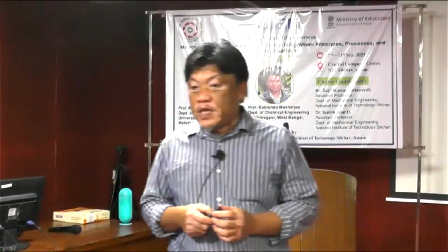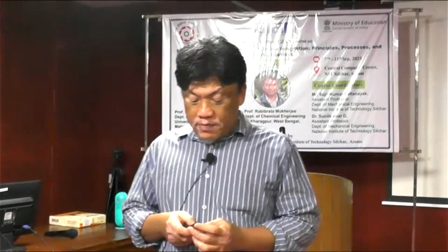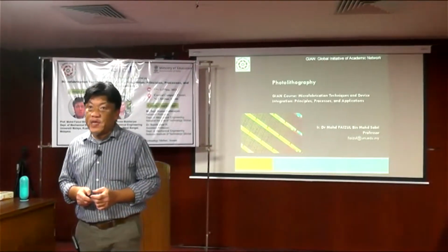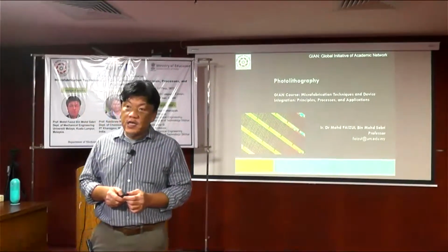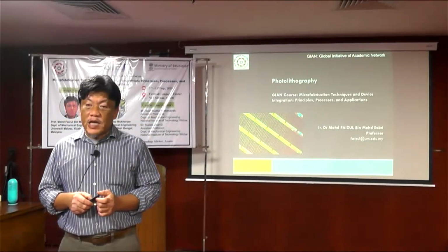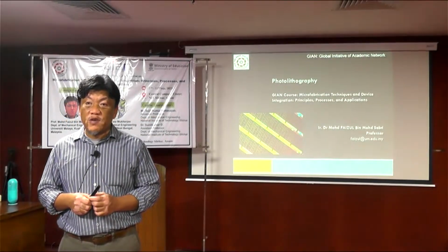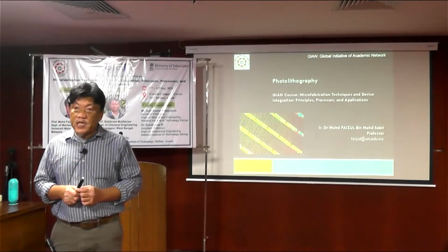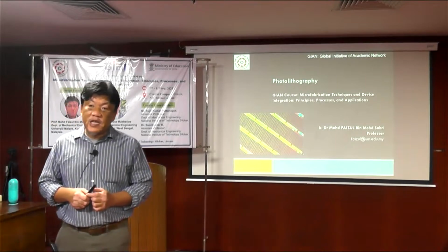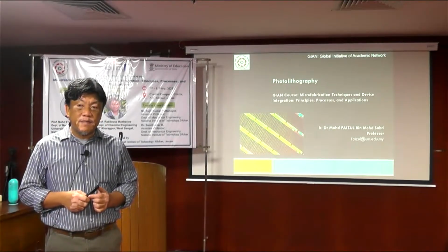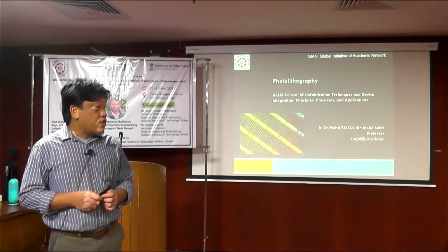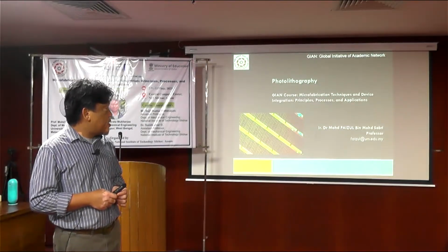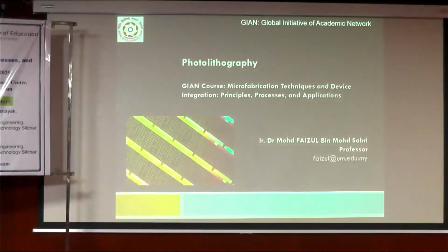Okay, and good morning. Still morning, and we shall continue with our next topic, which is microfabrication photolithography. The process, which is kind of the heart of the process for microfabrication. So that determines the capability to make it small, being able to make sure that we can produce a small size of the structure as well as the intended shape and structure as well.